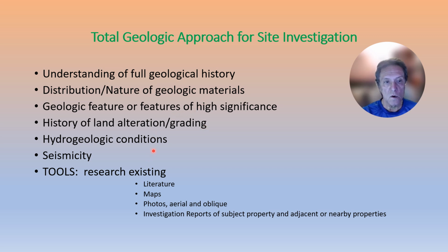Hydrogeologic conditions, of course, the presence and the depth of groundwater. Seismicity. As you know, in California, we have high seismicity due to the nature of California's location on the continental borderlands. So we're influenced by seismic activity from the San Andreas faults, San Jacinto faults, and locally in San Diego, the Rose Canyon faults.